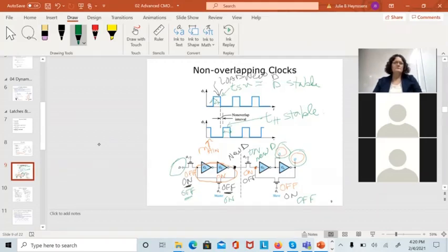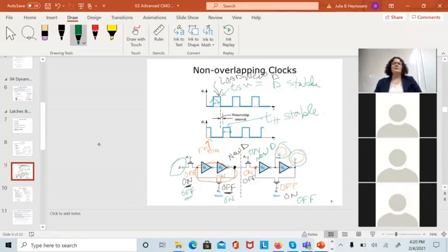Why don't we just take some RC? Because those are really hard to build inside integrated circuits. And slow inverters are really easy to build. I make the L big. I make the W small, and I can get it really small.